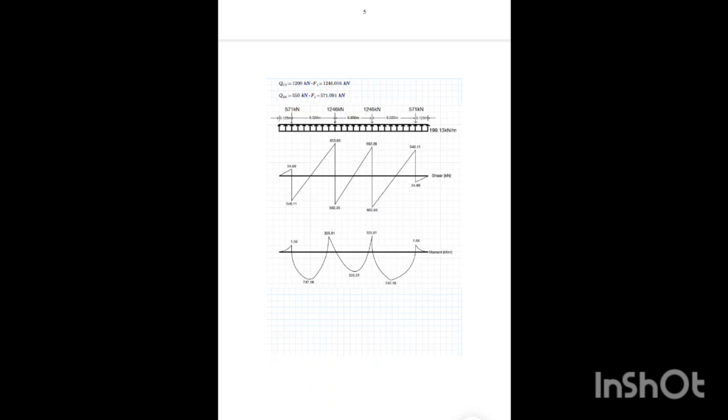Based on the shear diagram, the values that we will get are 24.89, 546.11, 653.65, 592.35, 592.35, 653.65, 546.11, 24.99. And from the moment diagram, the values below we will get are 74.16, 555.31, 747.16. The values above are 1.56, 325.81, 325.81, and 1.6.